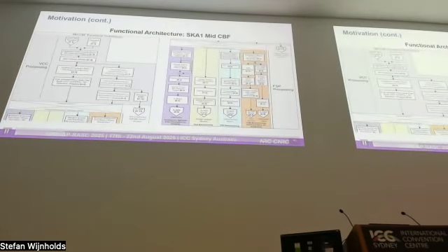This diagram shows the functional architecture of the correlator beamformer for the SKA mid-frequency telescope. Note that the key signal processing modules for the different observation modes include different analyzers, tunable filters, resamplers, beamformers, and cross-correlators. For the FX correlators, which involve multiple processing stages before performing correlation and beamforming, end-to-end models are highly efficient. These models provide a comprehensive framework for understanding how different modules interact and influence overall system performance. This understanding is crucial for diagnosing and resolving issues during both the development and deployment phases.